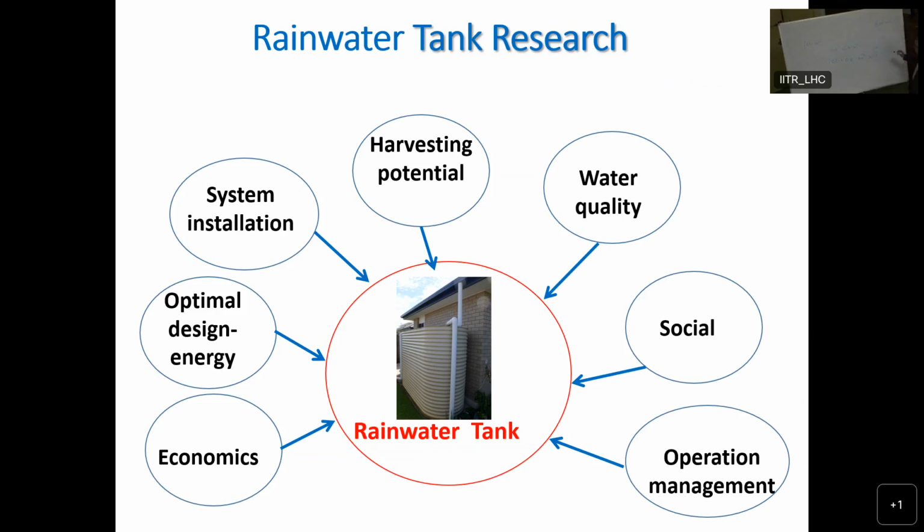if you see a simple example, we have a rainwater tank over here, which is connected from the roof. We are connecting from the gutters, okay? Down pipes. You have seen all the down pipes. Those gutters are designed to carry 120 millimeters per hour.